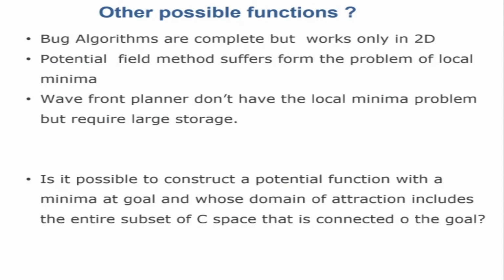So we have seen the other problems that are there. The earliest bug algorithms are complete, but they work only in 2D. Okay, the potential field method suffers from the problem of local minima. Now, wavefront planners don't have the local minima problem, but require large storage. So these are the problems that are there.